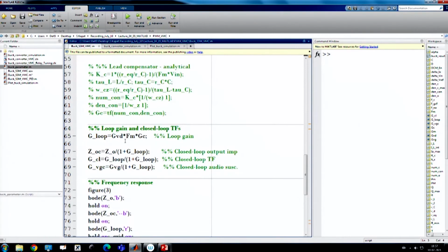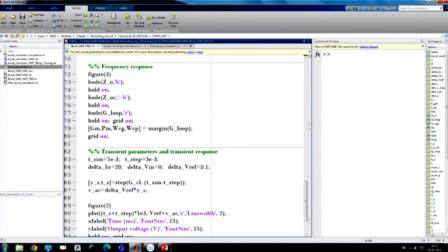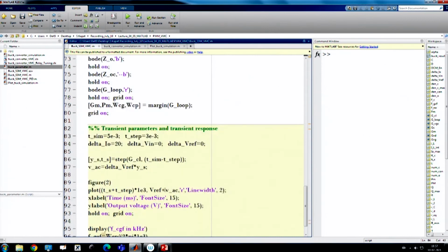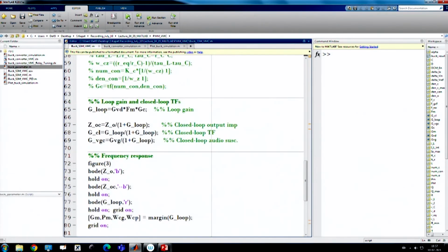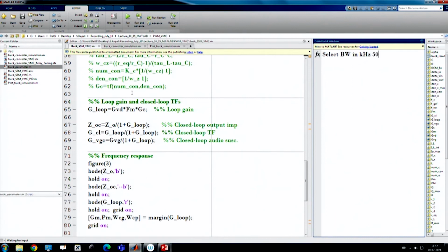So we are making a load transient, okay, where now there is no reference transient, and we have discussed that for that this will be minus of delta load step size, that means this size, okay, and here it should be output impedance, that means ZOC, okay.